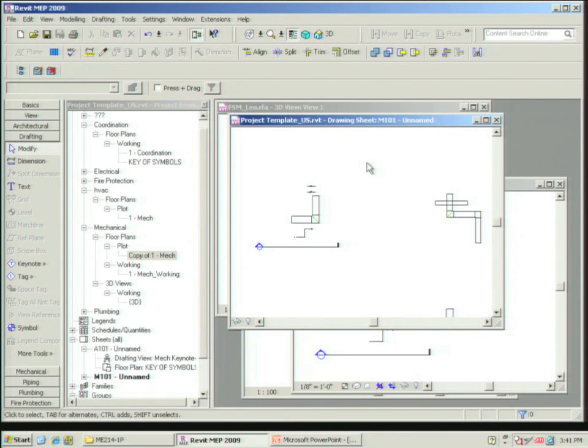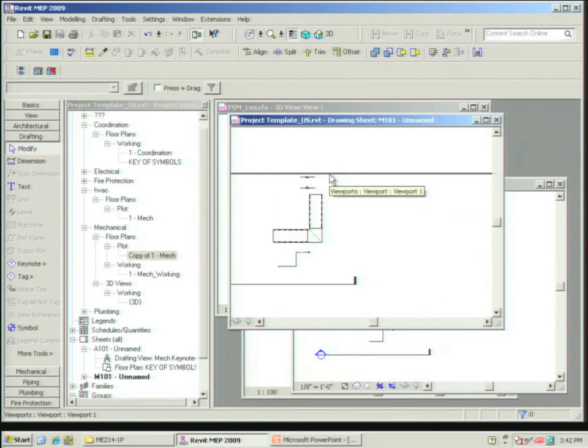So this is the only way you can show it, but of course there's a lot of downside, which is pretty much the same story as the view overlay, but it has more control. Let's say you made a transparent ductwork. How do you know later on that you made that ductwork transparent? Unless you wrote it down somewhere, it's almost impossible to keep track of it. But in this way, you put this ductwork on a separate workset and just set it apart, and make a separate view with a view template showing only that ductwork. So even if it's on the same floor plan, same ductwork, you're only having two different views just laying on top of each other.